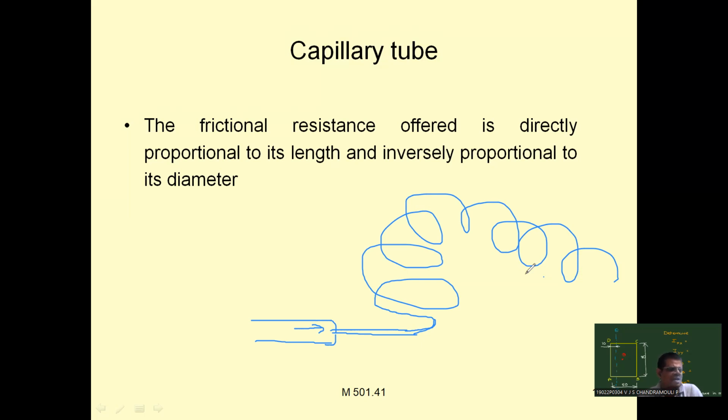So that's why we have to be careful while deciding the length of the capillary tube, as the pressure drop depends upon the length. As the length is increased, the resistance is increased. That's why the pressure drop is increased. So while calculating the length of the capillary tube to be installed, we have to take into consideration the required pressure drop.